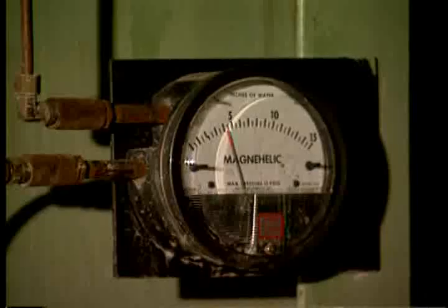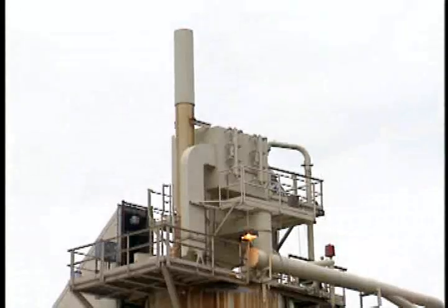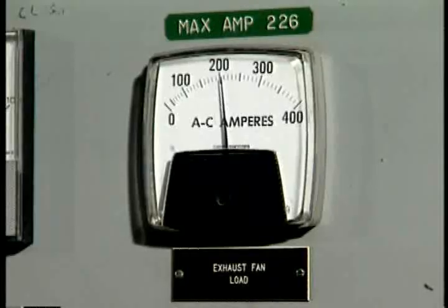But seriously, though, we also have real measures from gauges and meters so we can be sure that the water flow and power draw and pressure differentials are correct for each piece of equipment. We can also tell by using a special device whether we're emitting material into the environment. We can tell, for example, by reading this amp meter whether or not the pump motor is working that feeds water to the spray bars in the wet scrubber.